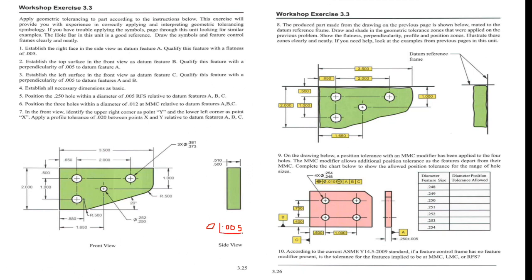This is the requirement, and I can say this is on this face, and this is my datum feature symbol. This is my datum feature A, primary datum feature.